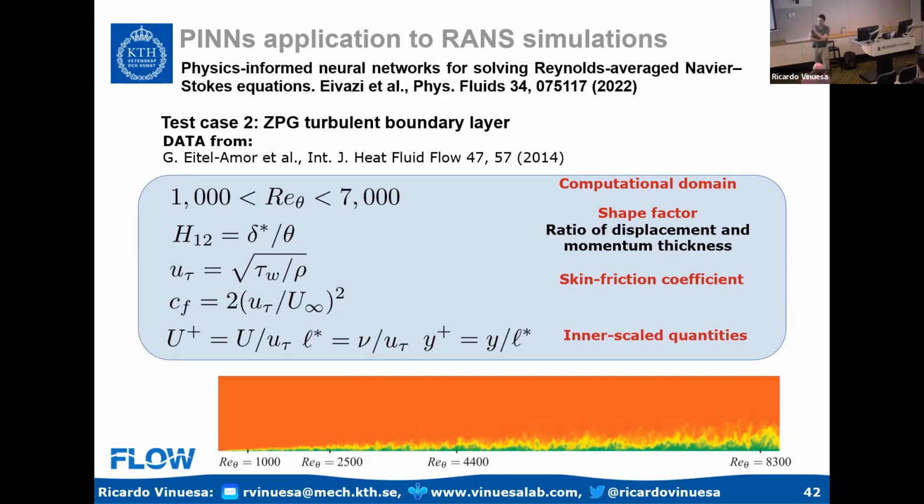I didn't show it today because it was only an introduction, but I can share the paper with you. We published it last year. We did it on a minimal channel. The main difference between real turbulence, even if it's just a minimal channel, which of course has simplified temporal dynamics, but still has all the ingredients of turbulence, and the 9 equation model is that the 9 equation model has only one scale. Everything happens in the near wall. But with turbulence, you have several scales. You have separation, even if it's a very low Reynolds number and it's minimal, you have some range of scales.